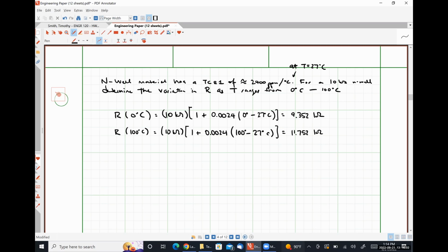Now, other materials like active material or high-res poly 2 have different temperature coefficients of resistance. So creating resistors out of those other materials tends to add complexity to the process, like literally the processing that occurs in the creation of your device, which costs a little bit more money, but you also typically get better resistor stability as well.